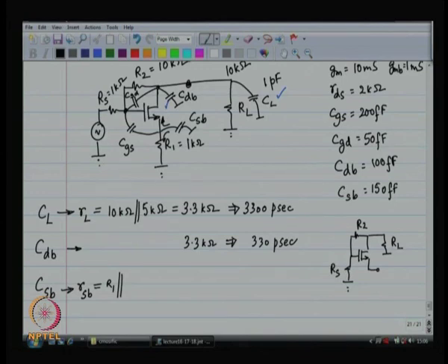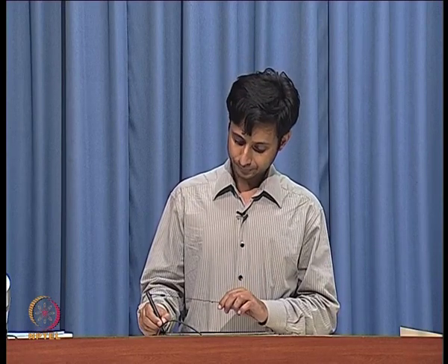That is my circuit over there. Okay. What do you think you are going to see? You are going to see a small resistance, large resistance. First of all, whenever you look into the source, you see a small resistance. So, if you see kilo ohms, it is most probably not right. If you see hundreds of ohms, maybe you have done a good job in the computation. Okay. So, let us try.